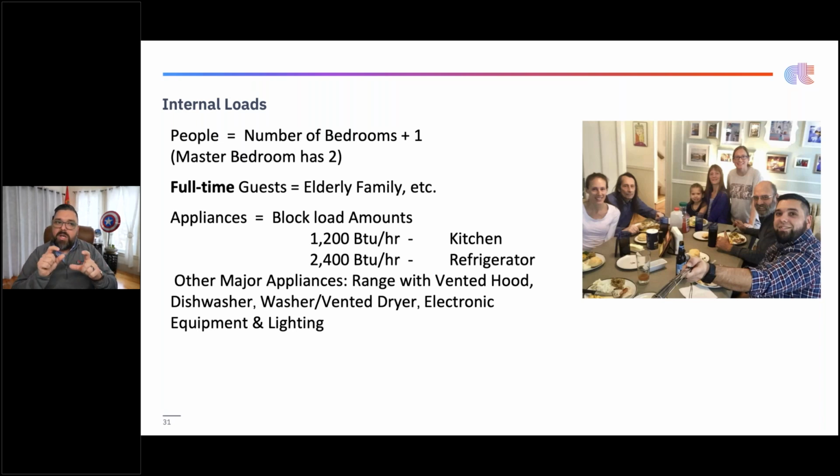There are also other additional things that you can add to the room specifically, like I have a couple of ceiling fans in my living room. The motors in the ceiling fan actually put off the same amount of sensible heat as a person. It's 250 BTUs. You have to make sure you account for that. Obviously not latent. People resting is 240 latent, but you have to make sure you account for that in your heat gain. Otherwise, you're going to be dreadfully short if you don't account for, let's say, all the can lights in your kitchen, or the multimedia stuff that I've added to my home office that they didn't have in 1880, right? So it's really important you account for all those things that could be running at 4 or 5 p.m.